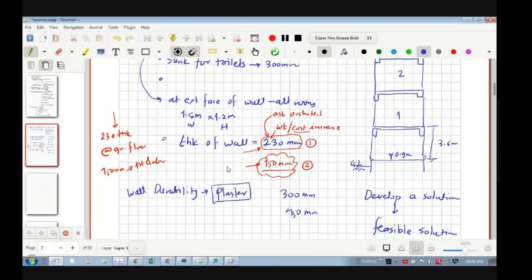But here they are only partition walls, so why take more wall thickness? So generally, I even recommend this to all consultants. Yeah, there is one via media. Generally, there are Ciporex and lightweight brick walls, which are available in 200 thickness also. So that can be a midway solution sometimes. But yes, you can discuss this. First of all, you should know that there is a 200 mm thickness wall available. There are lightweight partitions. Then there are 150 thickness available, 230 available through bond. So you can take that decision.